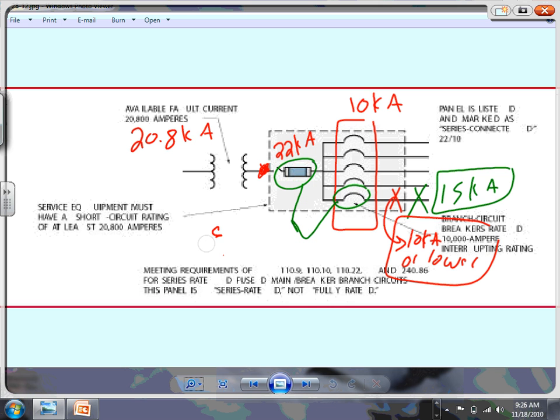So you're going to find most of the faults on the feeders are ground faults, and the ground faults are low, and most of them will be 10 or below. Most of them, not all of them. So if I want to give a percentage, this circuit breaker will protect me up to 90%. 90% of the time, this guy will trip, and only 10% of the time the main has to trip. I can handle losing the whole panel for only 10% of the time.